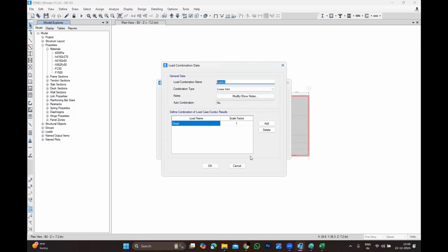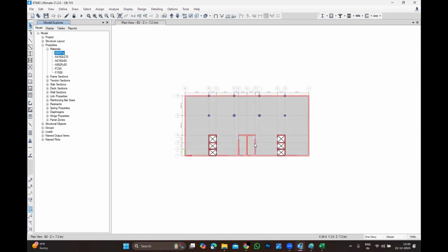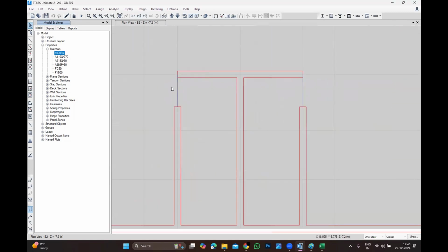Yeah. And sometimes people also do this: I model the beams here, right? Okay. Instead of beams, actually, I will model the wall. Then I will leave the opening. Then the wall will give you a bit more stiffness than the beam element, because a beam is called a frame.